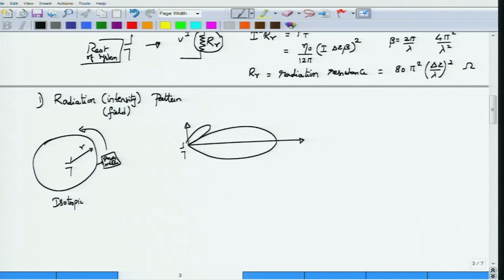In practice, you will also find what are called additional lobes or side lobes. There is also something called a back lobe. So, that antenna actually radiates backwards as well. So, this type of antenna is clearly not the same as an isotropic antenna, and in fact, depending on the beam and the number of side lobes, one can further characterize these antennas into fan beam and pencil beam. These are called beam patterns or beams of an antenna. So, the pencil beam would basically have its radiation along very narrow angles.